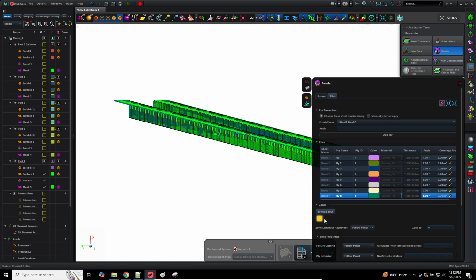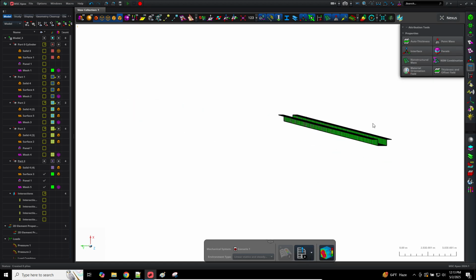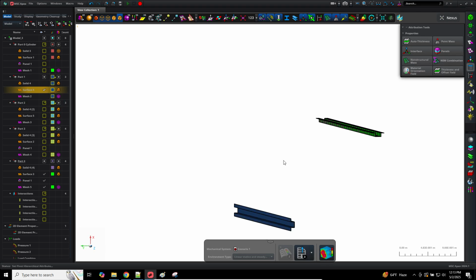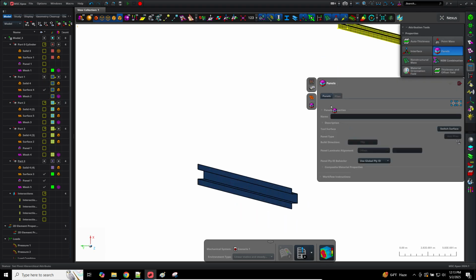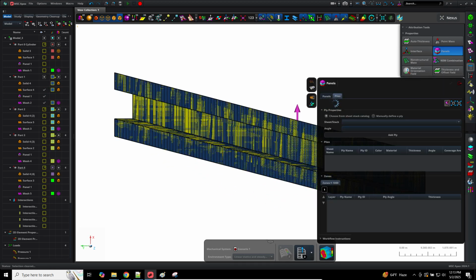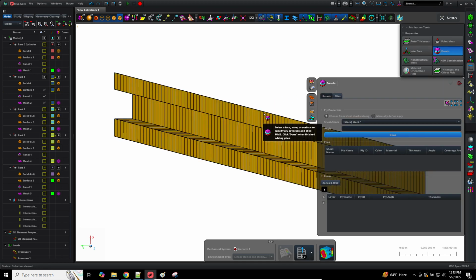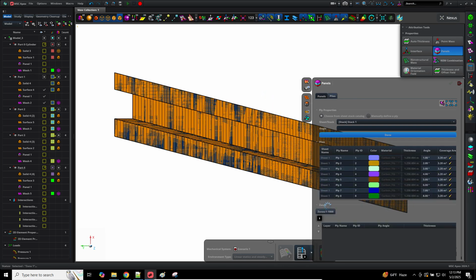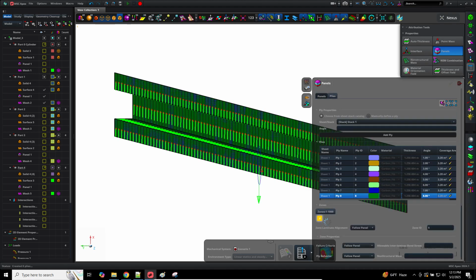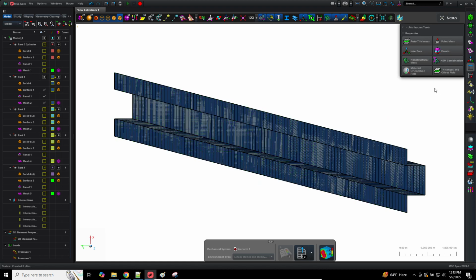I don't know if that last part is necessary, but I've just been used to it, so let's close here. And then let's see, what else do we have? Let's focus on this stiffener. So go back to panels, select this object, click the scroll wheel, go to applies, select this stack, add apply, select this, click the scroll wheel, and then here, again, I don't know if it's necessary to click the zones icon, but I like to do it. It's almost superstition at this point.